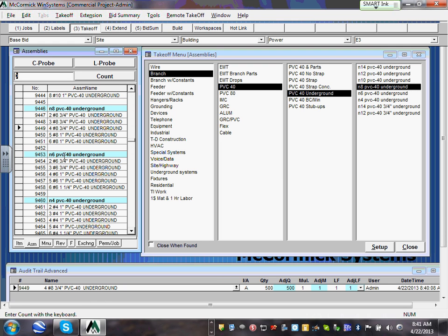So what I actually get is the size of conduit based on the wire size that we're using. Yes. What size of wires do you guys use? 10? Yeah, so if we switch to a 6, it'll pick a different one. Yep. You're going to pick it based on the design that you guys have done. You have to use at least number 10 outdoor. At least number 10. Okay.